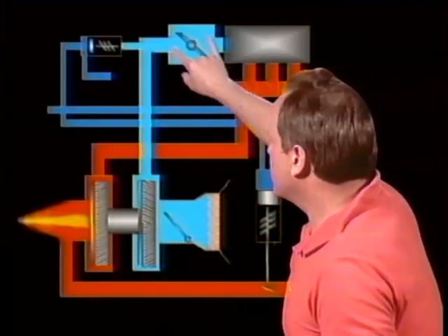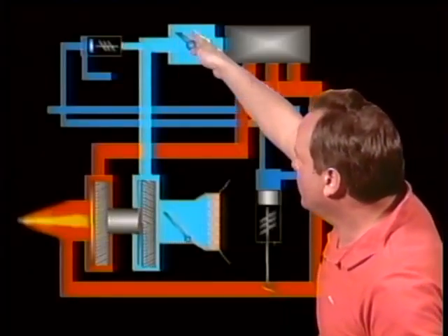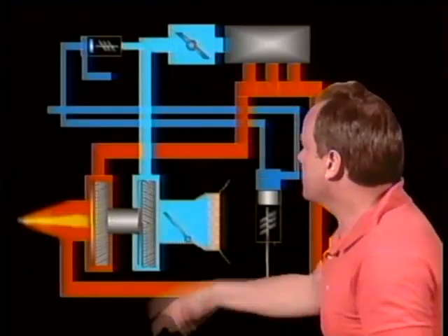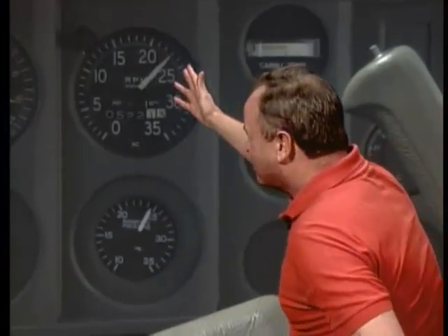That's the density controller. So now let's take a look at what is the purpose of the differential controller. Well, the differential controller does something different, and that's the one that measures the pressure on each side of the throttle valve. It functions during all positions of the wastegate valve other than the fully open position. It's constantly working except when you're fully open and then the wastegate closes and you're driving the turbocharger as hard as you can. Now here is something that can happen in a turbocharged airplane that's considered to be a bad thing. It's surging, and this surging is caused by what they call bootstrapping.